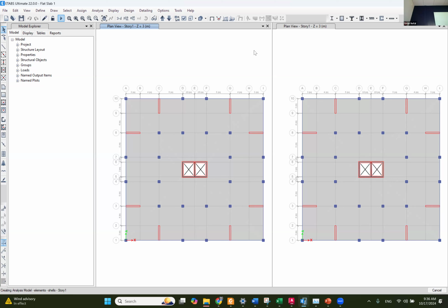We're gonna wait until it finishes the analysis and see how it looks. And I'm gonna show you how exactly the same process of replicating the story looks in SAP 2000. Do you guys remember how we did replicate in SAP 2000? We select this story without the boundary condition or the fixation in the first floor, and we hit Edit, Replicate, and then we list how many stories we want to replicate. So we are gonna do the same thing here and see how it's different.